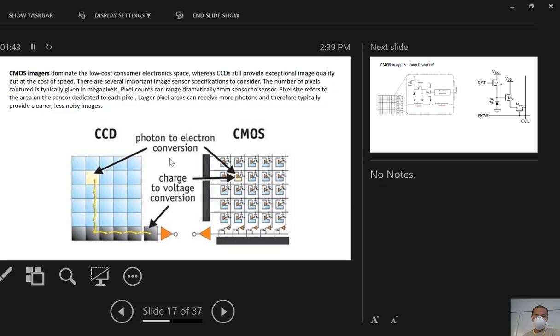So that's CMOS materials. And that's why we can integrate millions and sometimes billions of pixels in a tiny area. And that's a camera chip. So the camera chip is actually a CMOS chip. You just lay out a photodiode, just a pin junction for each pixel, and a little capacitor to hold the charge, and then a row decoder, and then a row of ADCs.